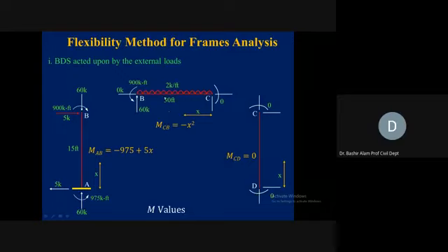So 2 times 30, which is 60. This total load of 60 is going to be balanced by B, and from B it can travel towards the support. So vertically, this member BC is in equilibrium: 60 in the downward direction and 60 in the upward direction. Horizontally, if this horizontal is 0 and here the horizontal is 0, so horizontally also it is in equilibrium.